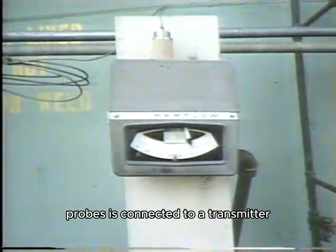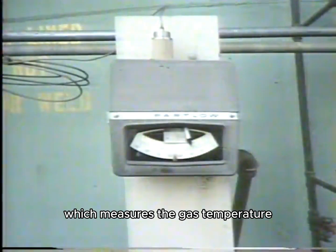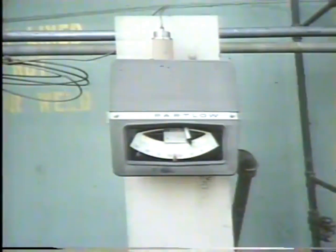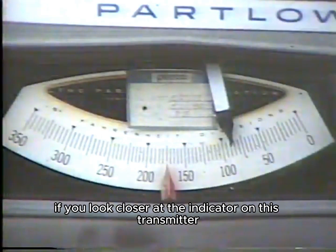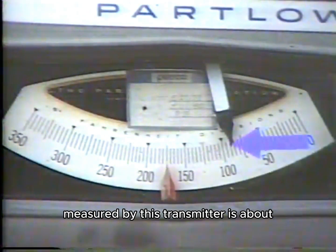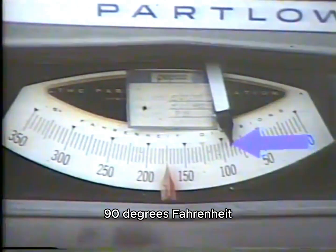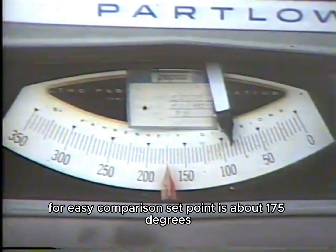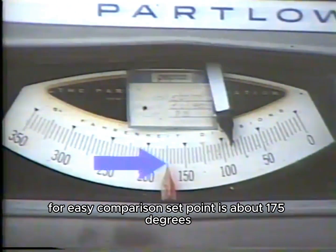Each of the temperature probes is connected to a transmitter, which measures the gas temperature indication from the probe at that point in the scrubber. If you look closer at the indicator on this transmitter, you can see that the temperature indication measured by this transmitter is about 90 degrees Fahrenheit. The set point of the controller is also indicated here for easy comparison. Set point is about 175 degrees.